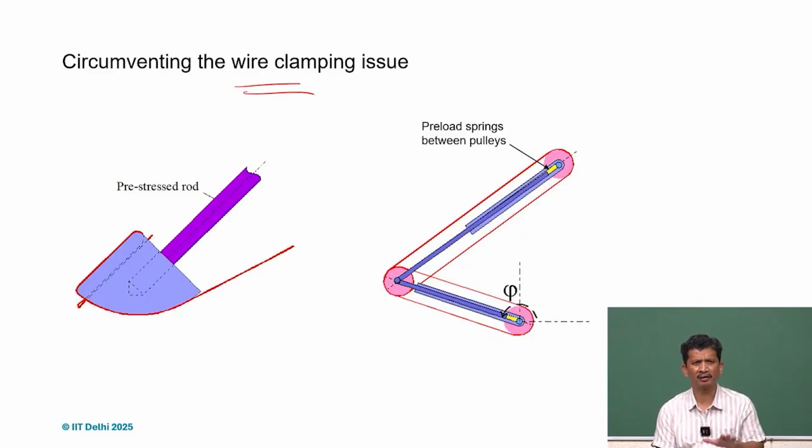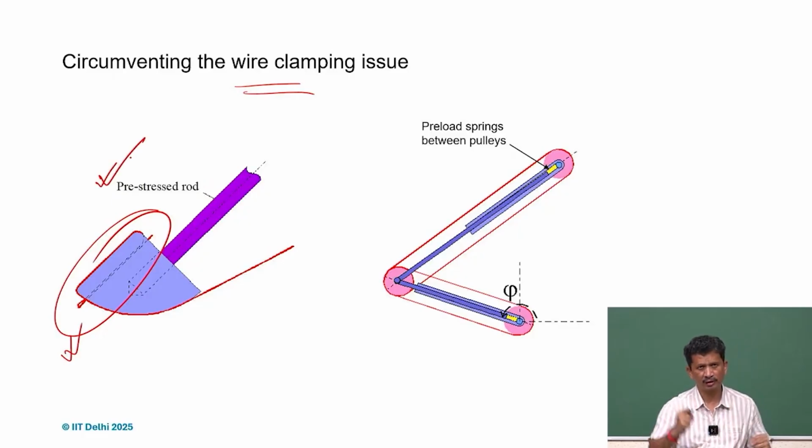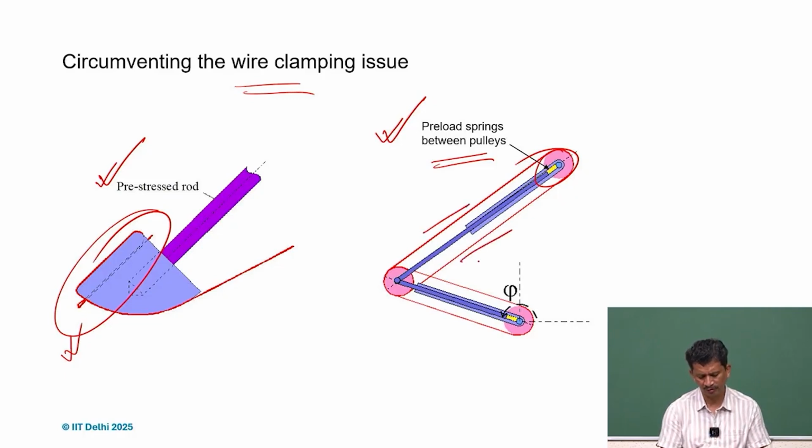So many parallel guideways are secured using cables. So this is what is there. Yes, clamping is an issue, so many times we have to check how to route it and then clamp it, and pre-stress it to get that tension in the cables. And like in many designs, we can have springs here as pre-tension, so that the loading here is always in tension.